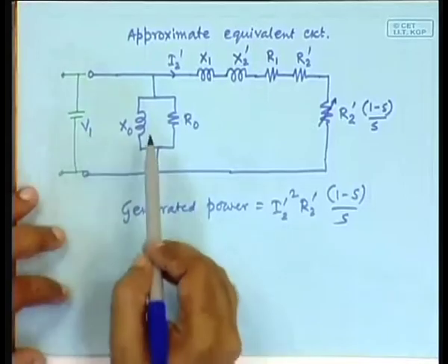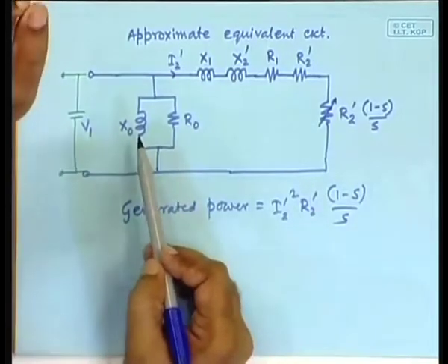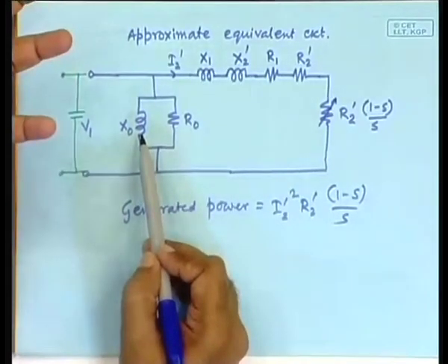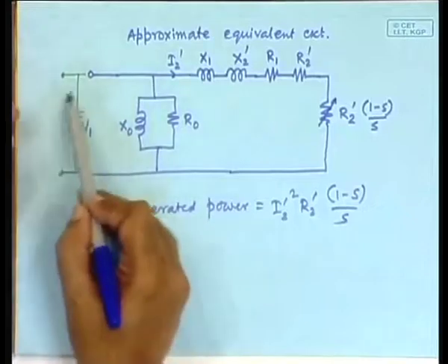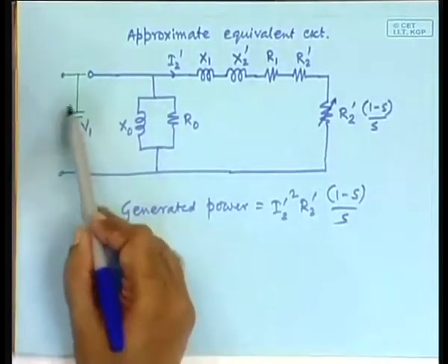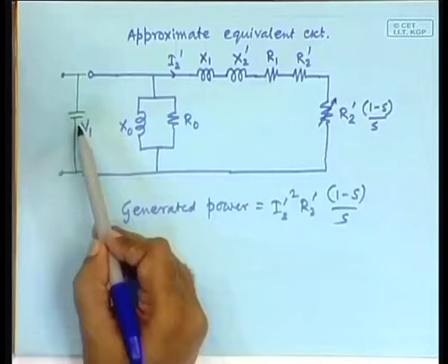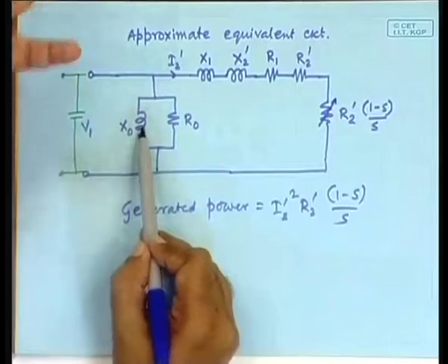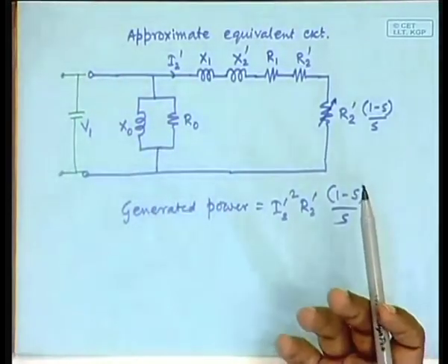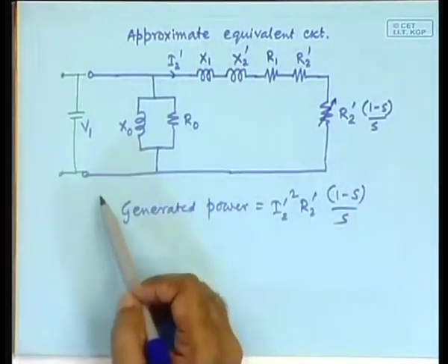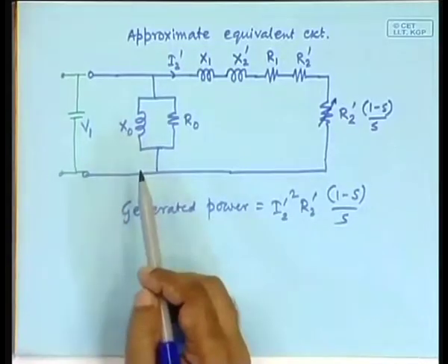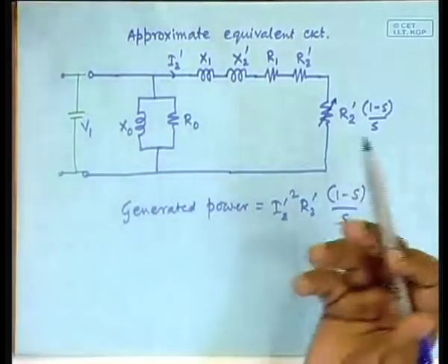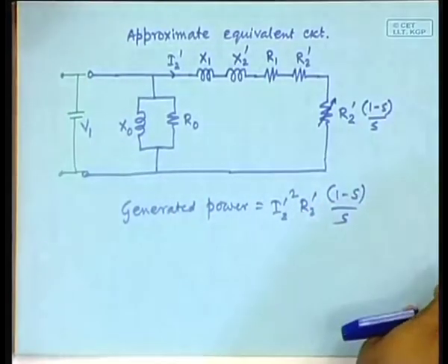Then if there is a little bit of residual magnetism, as the rotor turns, there will be some amount of voltage generated, and that will generate a small amount of reactive power in the capacitor. The capacitor will produce some amount of reactive power that will be pushed into this line. As a result, the magnetism will be enhanced, and in the same way this machine can also self excite. But in order to understand how and in what way, let us go through this process.